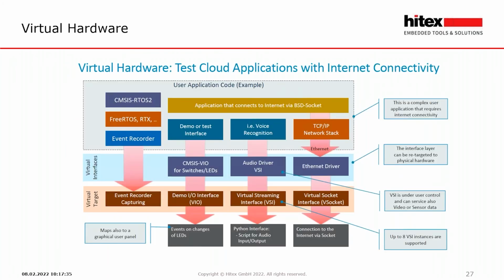So here we have the simulation environment. So we have the Cortex processor that can support our application code and various different small footprint operating systems. And in addition to that, we then have virtualization of common streaming interfaces. So for example, I think the first one that they have in there is audio streaming, so for keyword recognition, and also a TCP/IP streaming socket as well. So we can build up IoT systems.